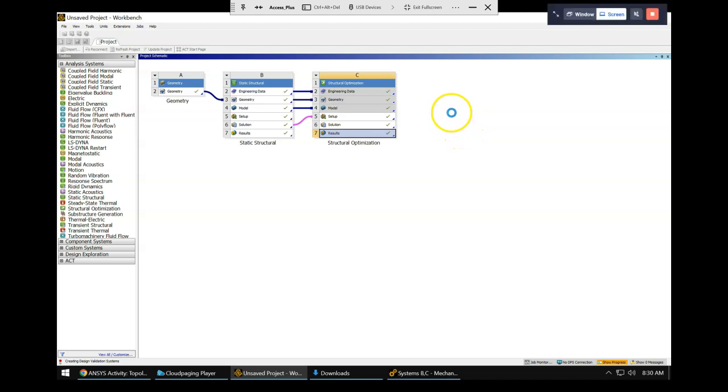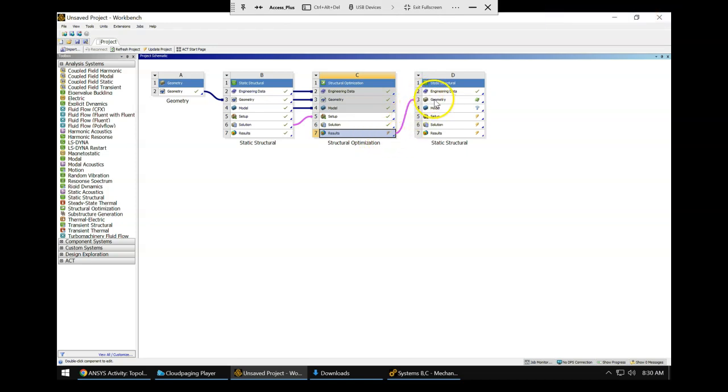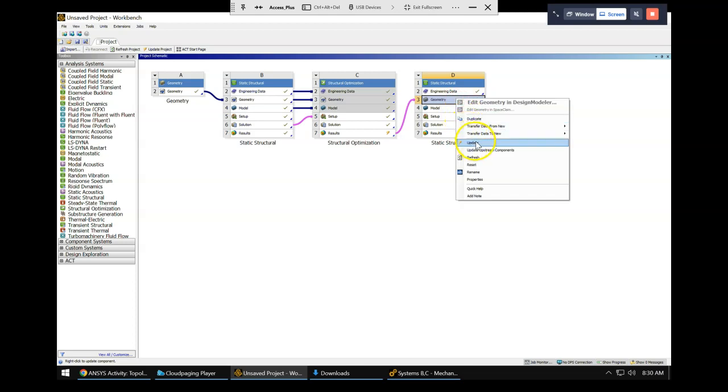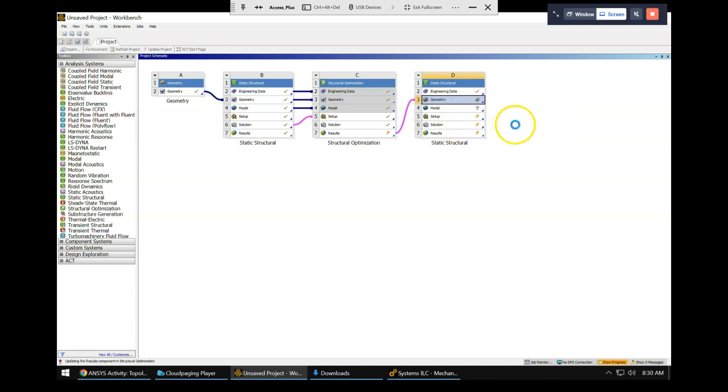That's going to take a little bit to appear, okay? And so what it does is it connects the results into the geometry of that block. Right now I can't do anything with that block. It has this little green refresh. So what I need to do after that appears is right-click it and say update. Why it didn't do that while it was doing whatever it was doing is a good question, but I think it's related to that retain threshold. If we change that, then we'd have to right-click it and say update. So there's this connection, and it doesn't want to do that automatically.